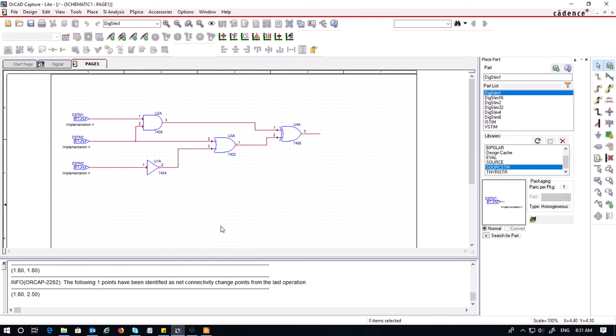Make sure you keep saving your circuit. All right, so the circuit is ready. Again, it's just a random circuit with 4 gates, and I'm gonna create some inputs, sequences of 1s and 0s, using these digital stimuli, and then we can check the signal at different points. In this case, I'm just going to check the signal at the input and then at the output, which is my U4A. I'm assuming that is my output.